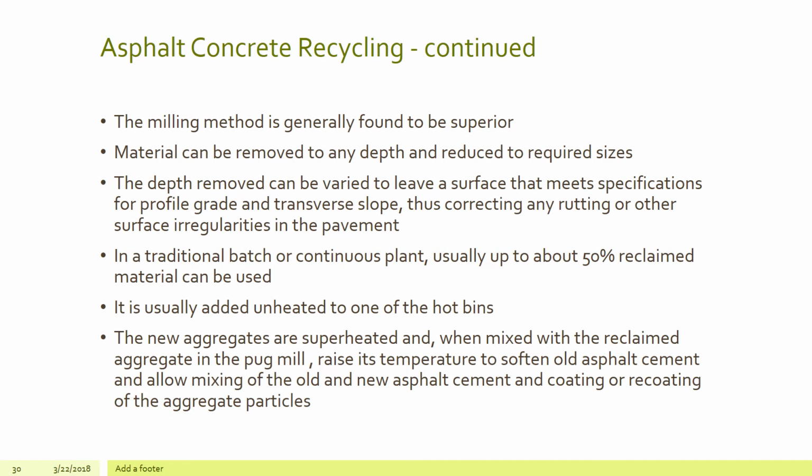The material can be removed to any depth and reduced to any size as needed. As I just mentioned, the depth removed can be varied to leave a surface that meets specifications for profile grade and transverse slope, thus correcting any rutting or surface irregularities in the pavement.